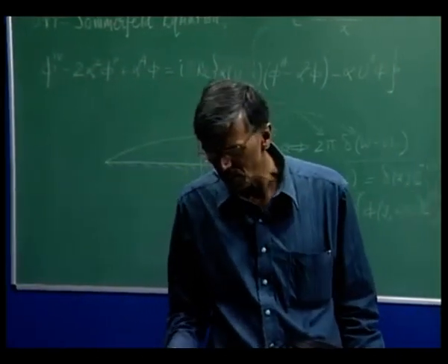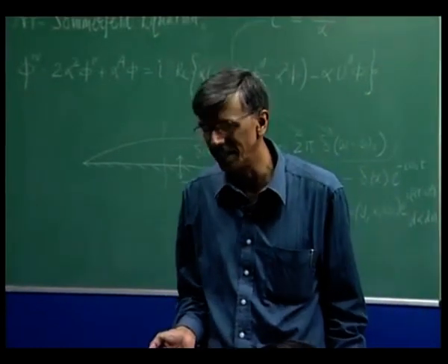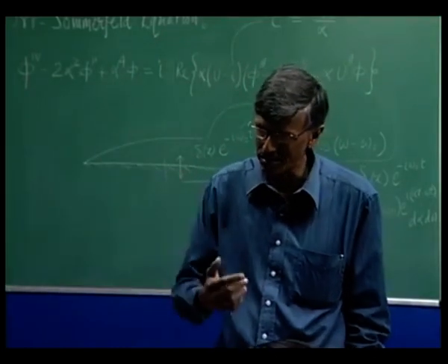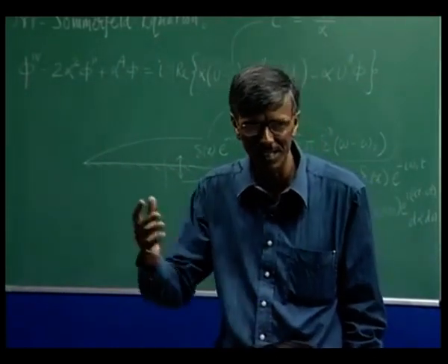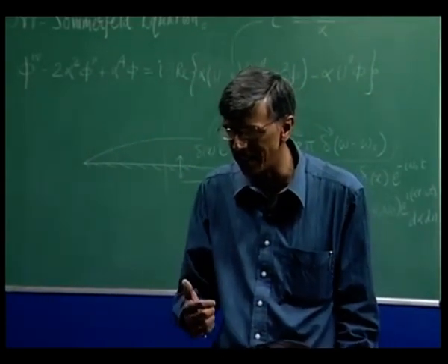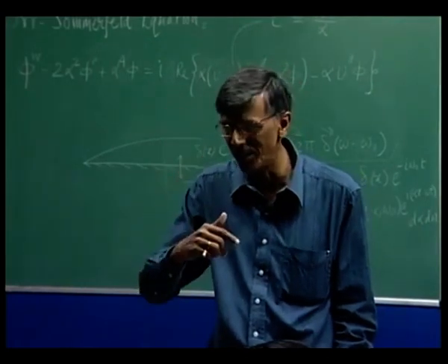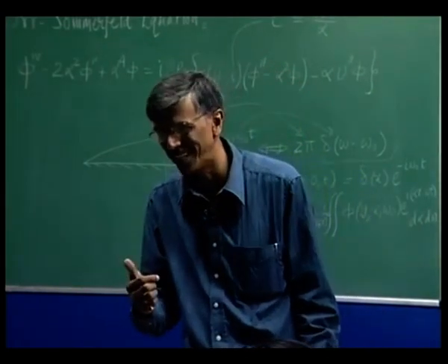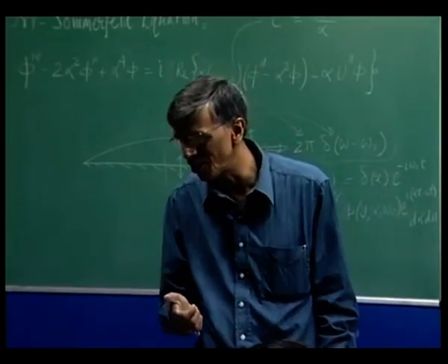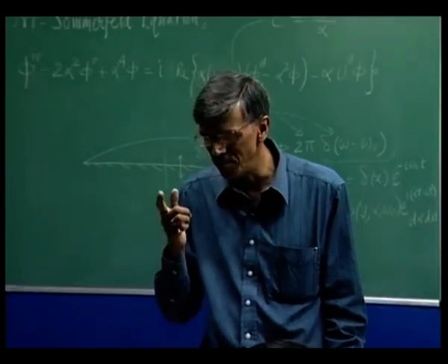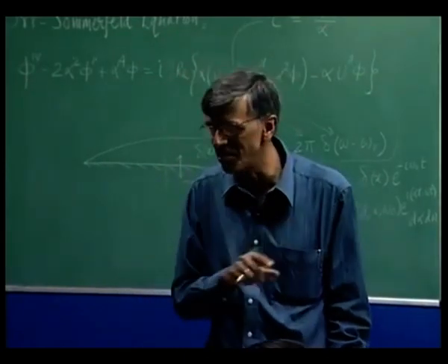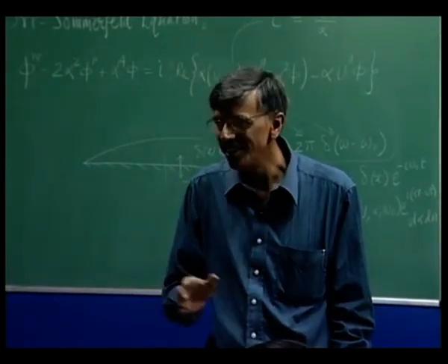For example, talk about clear air turbulence. There is a case by which we have figured out that if an atmospheric convected vortex is approaching the aircraft wing, then a pilot can decide whether to go over it or below it, provided he knows the sign of the vortex. If you are talking about a vortex which is rotating counterclockwise, it would be very, very advisable for the pilot to duck under it, and then instead of destabilizing the flow, it will stabilize the flow.